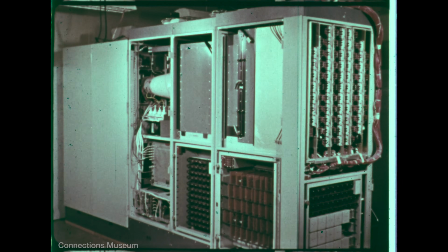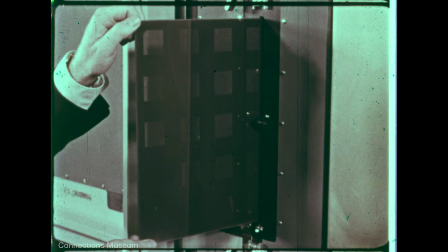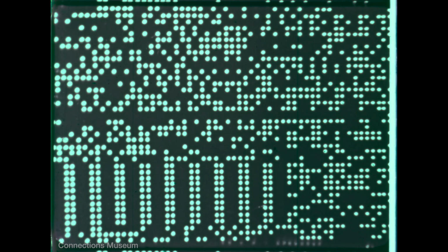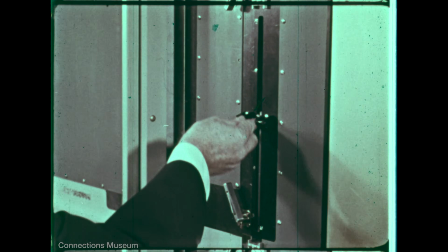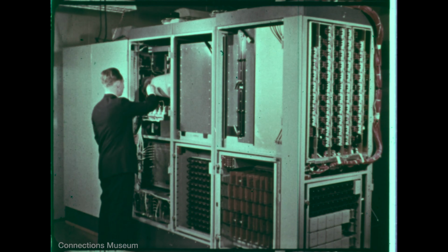However, the principle of the cathode ray tube has also been applied to a permanent information storage called the flying spot store. It's truly a photographic memory. On glass photographic plates, in each of 68 square areas like these, 65,000 tiny transparent or opaque spots are photographically printed. The spots provide yes-no answers when swept by a moving pinpoint of light from a large cathode ray tube.